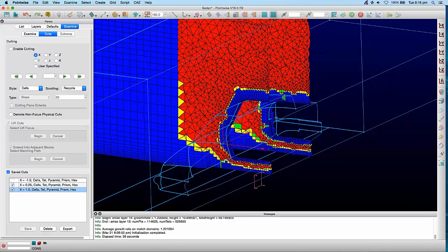Yeah, so the CFD is usually not done on the track, and a lot of the time GRM would do a lot of different configurations and use the CFD to give them what you'd probably normally get as a gut feel after observing the car and tweaking a car over several years of going through the races. So you can go into some of these pits where you've got some very experienced race engineers that have been working on the same car for the last 10 years or so, and they'll know what they have to do to tweak the car to get it to perform.